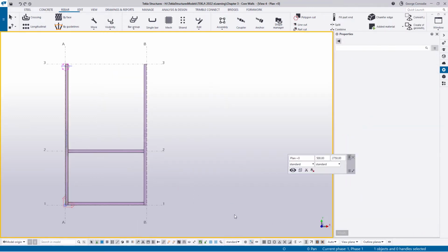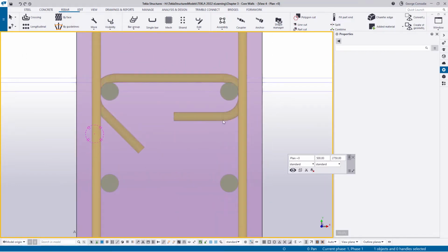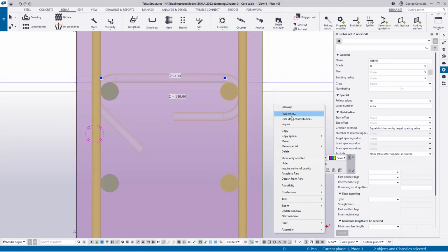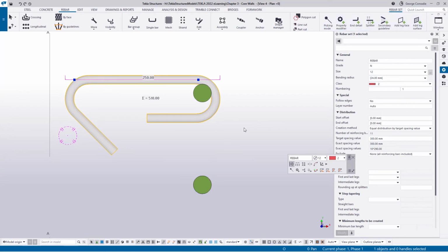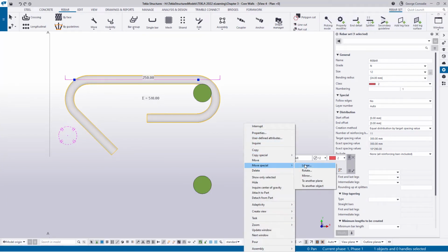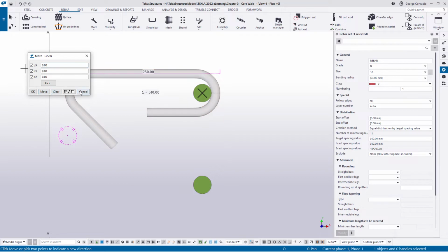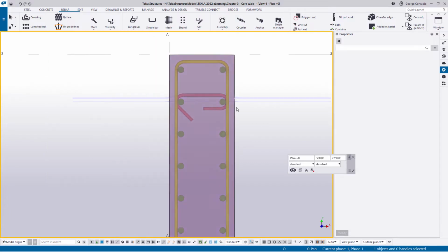And then if we go back to the top and have a good look at where that bar is, you can see what I mean about it not being in the center. So what we can do in this case, I'll click on that bar and I'll click on the vertical bar, select them both, right click, hold in my shift button and say show only selected so I can see the two. And now what I can do is click on this bar and say move in a linear fashion from the middle of this point to the middle of this point. Now I get a lot of values here, but all I care about is the y value. So I'm going to make sure that I zero anything that's in the x value and say move. And just like that, it moves that clip nicely onto that. So if I do a redraw, I can see that clip is nicely in here.